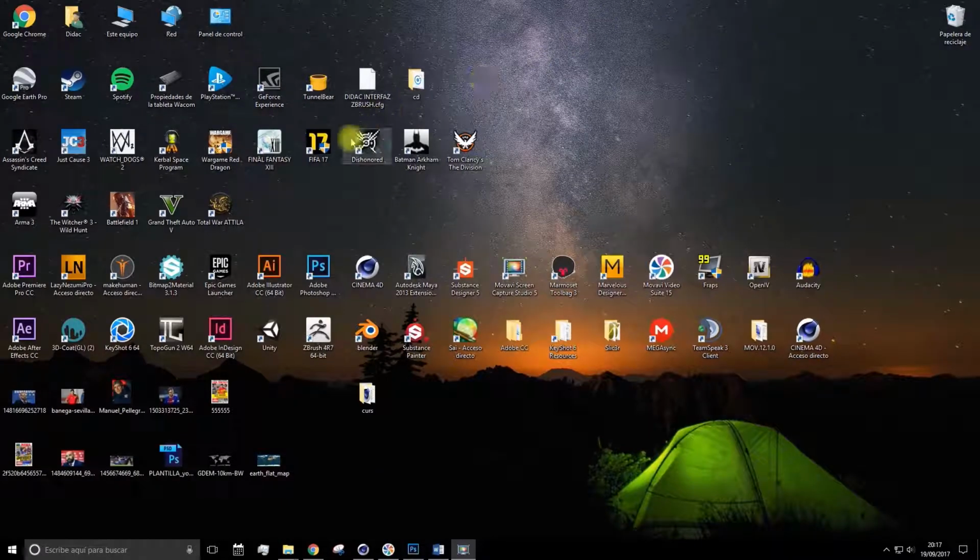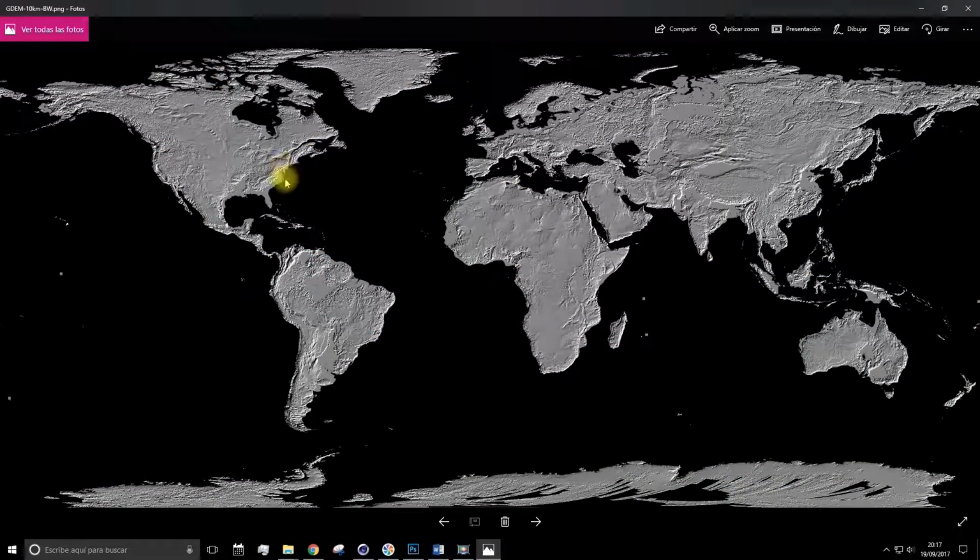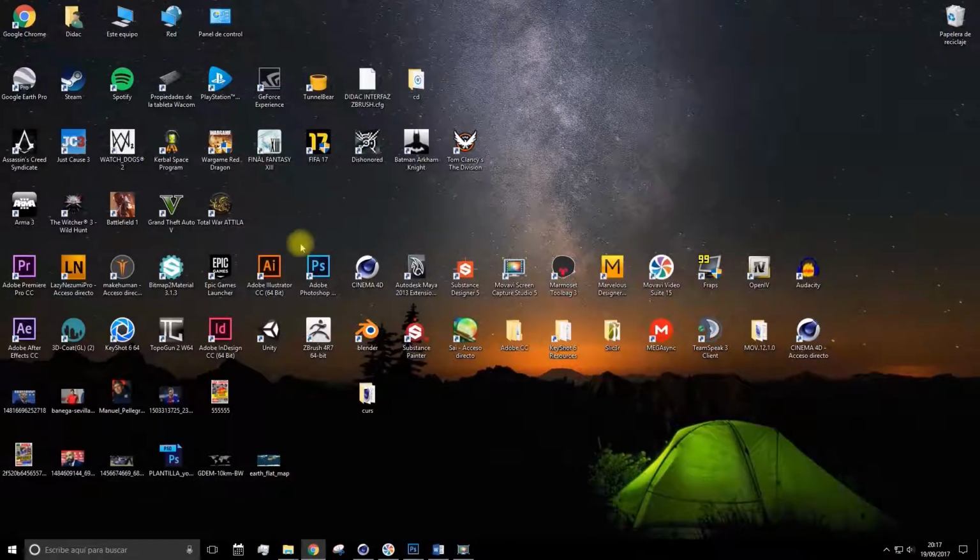A height map is basically a texture. So the 3D program interprets the black and white areas of that texture to generate volume. So in this case, the white area has more of a relief than the black. So really it's another way of modeling. Only we're getting the volume using a texture instead of directly modeling the object as we've done up to now.